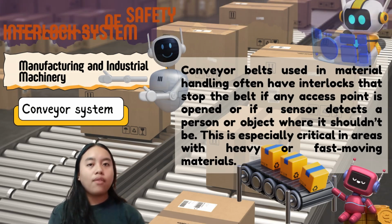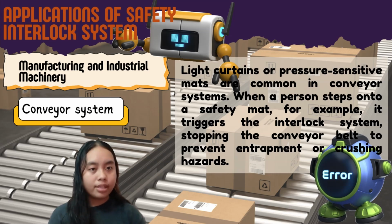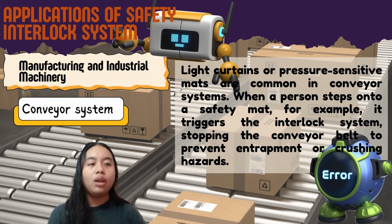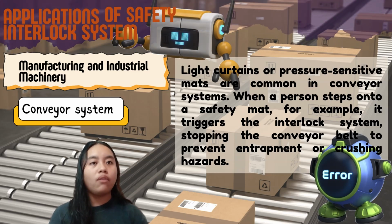In addition, light curtains or pressure-sensitive mats are common in conveyor systems. When a person steps onto a safety mat, for example, it triggers the interlock system, stopping the conveyor belt to prevent entrapment or crushing hazards.